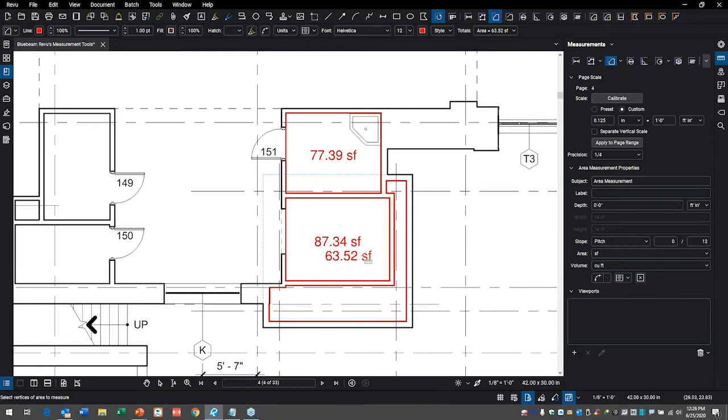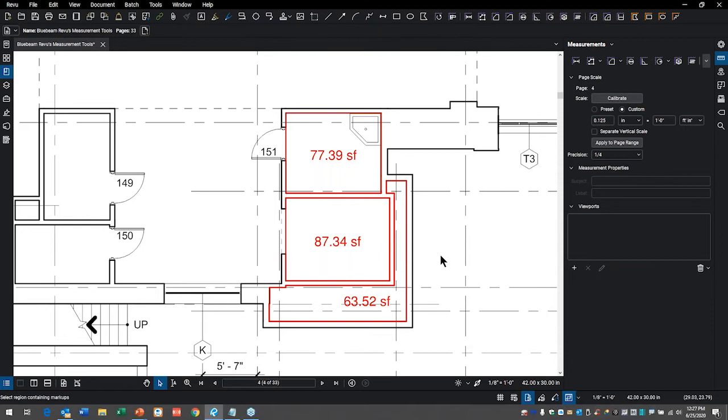Now, you'll notice that it snuck that information into an awkward spot. You can always hold down the Shift key and move that text, apparently except for angles and radiuses and diameters. I'm waiting to hear back from the Bluebeam tech people on that, but I think the answer is going to be no. So that's in its really basic form, right? So you can very easily do those kinds of areas. You can go ahead and do two other kinds of linear measurements.